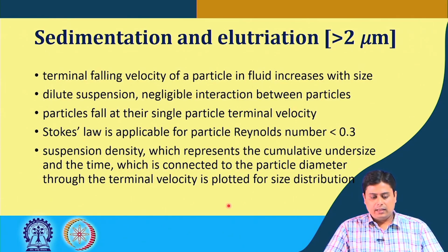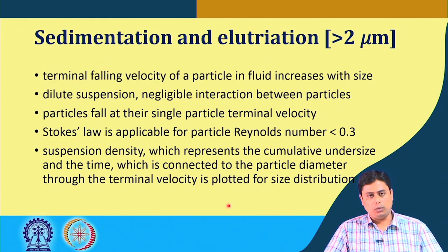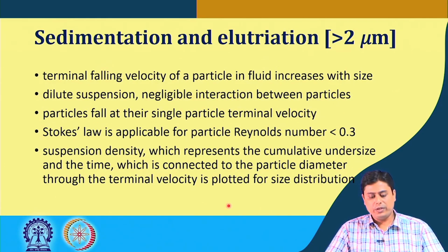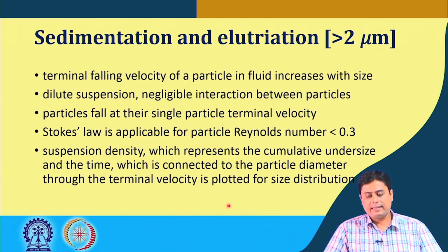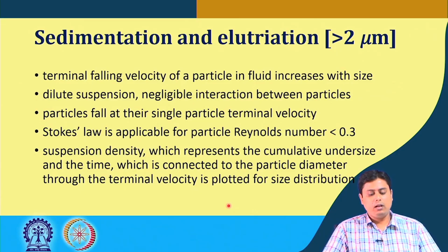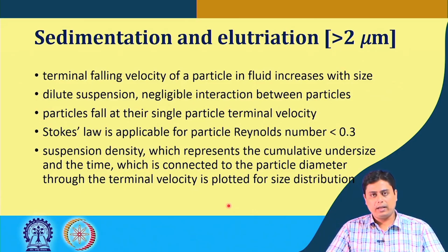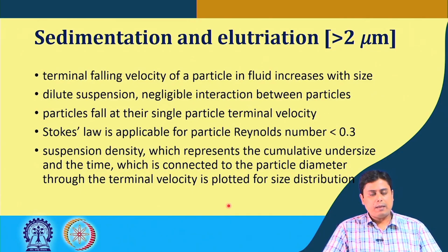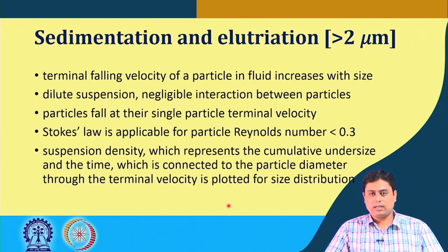In this technique, based on that fact, we typically apply Stokes' law, which is applicable for a particle Reynolds number of less than 0.3. Also, you may remember that Stokes' law is applicable for low Reynolds number cases, and it is applicable for dilute suspensions, where there is negligible interaction between the particles.